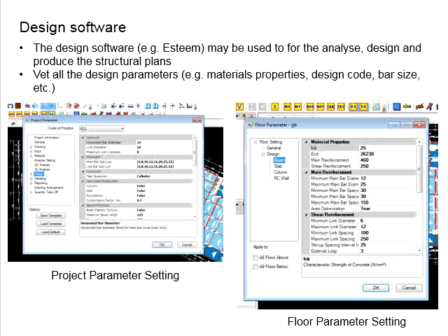And then once you have the loading confirmed, you will need to produce the key plan in the software. This key plan is on the basis of the architectural drawing. This is where you assign the size of the member, the size of the slab, the size of the column, etc. The process will be basically similar to what we discussed about the structural key plan in the previous videos. You will pre-assign certain common sizes first for the software to help you run the analysis.